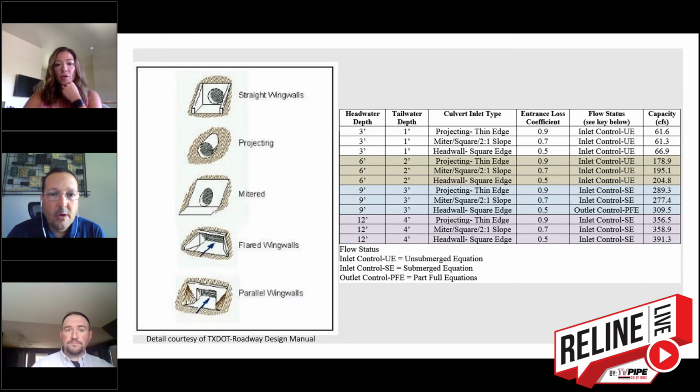Right. So a question for you guys, sorry to interrupt you, Don, is when would you use the HydroBell versus the reducer? Since you're saying that the HydroBell is flush and the reducer would bring it out, when would you use the two and why? We typically prefer the HydroBell to be used in most situations.